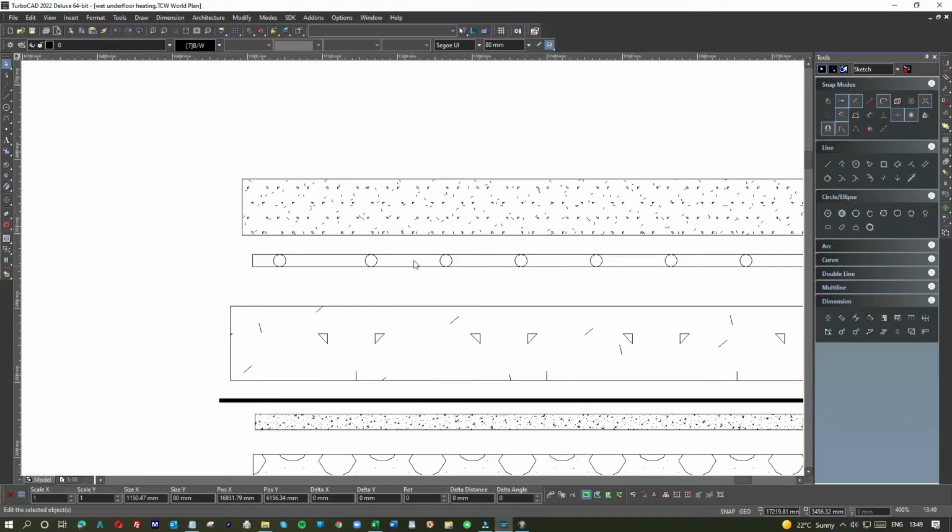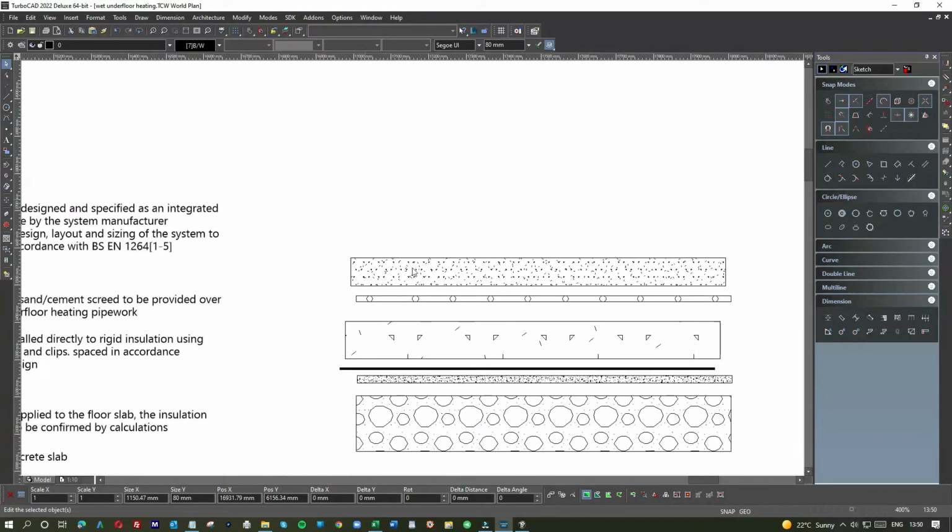For example, that's a finished concrete screed that can vary between 50 and 75 mil. It also depends whether you want it to go off quickly to be available to walk on the next day or within a few days. There are cost implications on those decisions.